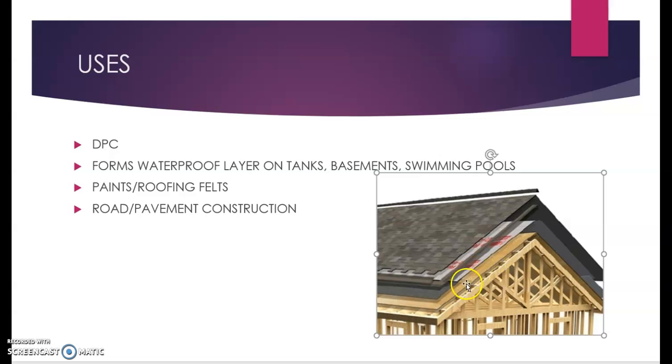This is placed over the deck slab, and over that your tiles are placed. Why? For many reasons. One is waterproofing, second is fireproofing, third is heat insulation. You don't want the heat from the top to travel down. Of course it adds a little bit of cost, but in the long run the maintenance part is very well taken care of.